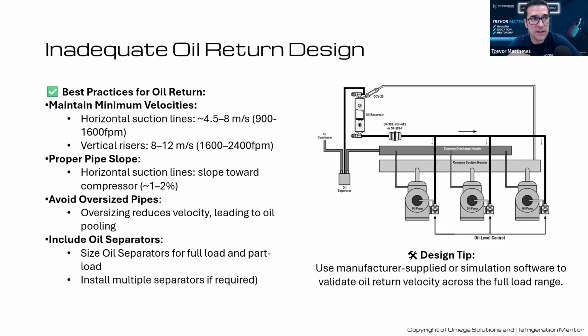I've seen it on old renos that I used to do, where sometimes they did not have any insulation, they did not have traps. They're like, oh, well, it's only 3.5 feet or a meter. You don't really need a trap for that because it's not high enough. But I've seen when I cut out coils before, they were just full, like the whole bottom of an evaporator full of oil. Lots of times. Completely oil logged. Just what you want to do when you're ripping them apart is get covered in 2 liters of oil. Yeah. So onto basically how can we actually encourage oil to return or not log in our evaporators?